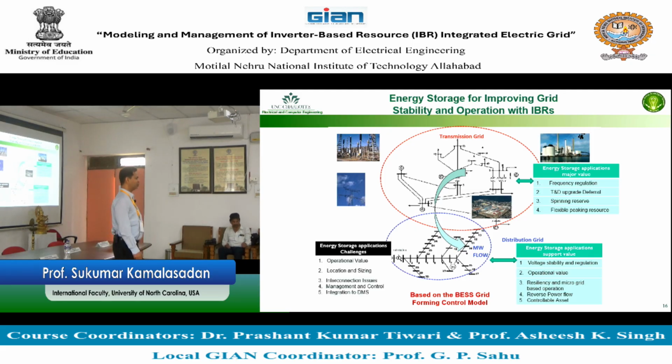So we have 250 kW in battery and a 1 MVA inverter. If we want to deliver 500 kVA from the inverter, which is half of the capacity, we said that we need around 80 kW active power from the battery. Then only can you actually do 500 kVA coming from the inverter. And where does that 80 kW go? It goes internally to take care of the losses. So reactive power support also needs some level of active power contribution from the source.